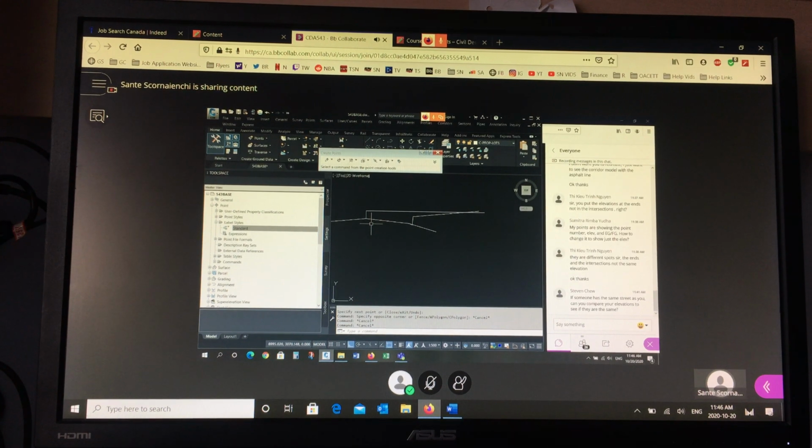I'm using AutoCAD to demonstrate what I'm saying. I'll show you how to do it in a moment. But do you understand why we're going to use the existing centerline elevation, add 0.3 vertically, and then use that number on the street line? Because that will be compatible to a future boulevard elevation. Okay. Now, is it going to be exact? No, but it'll be close.